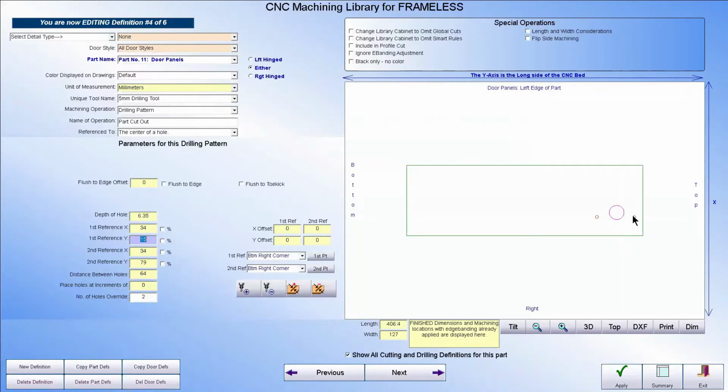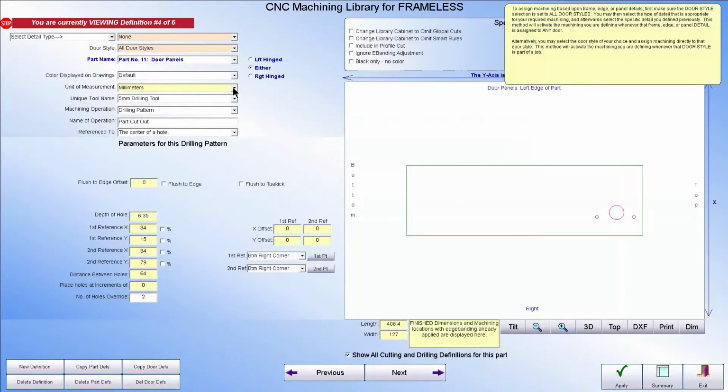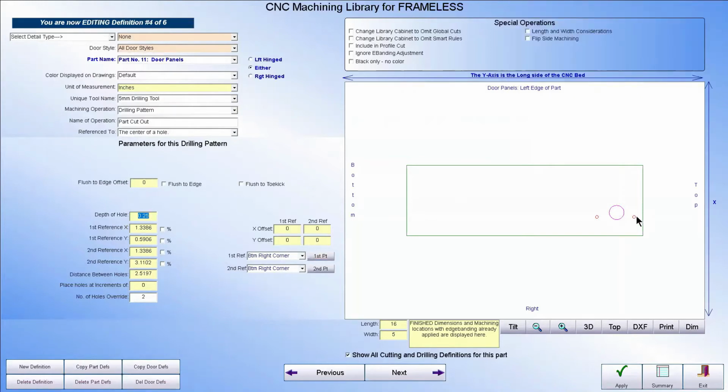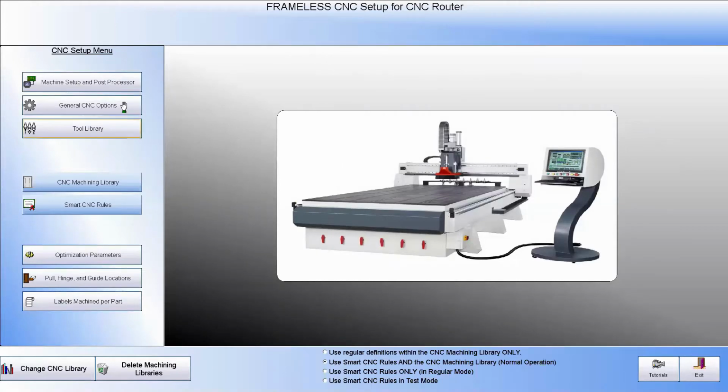Now, the drilling operation, we do not want to go all the way through. So we can put this in millimeter and inch mode, and you'll see that we're at 1/4 of an inch. Sometimes you want these screwed in holes to be just a little mark. So instead of 1/4 of an inch, you could tell that you want the depth of cut to be 0.02 inches. That'll just touch the material itself. It depends on how you want that done.